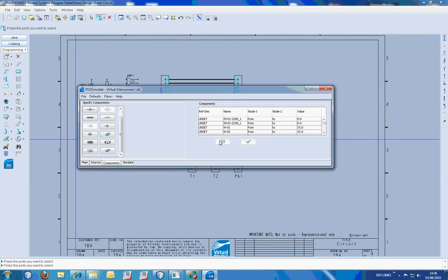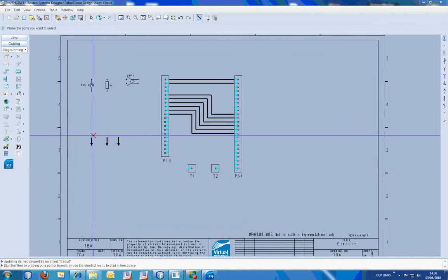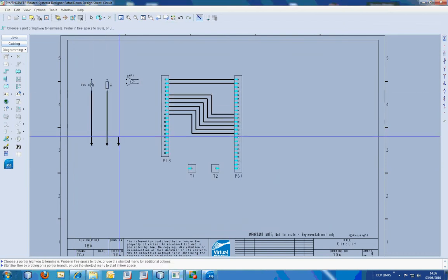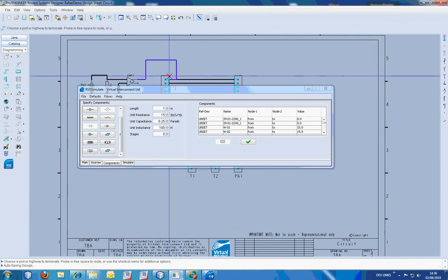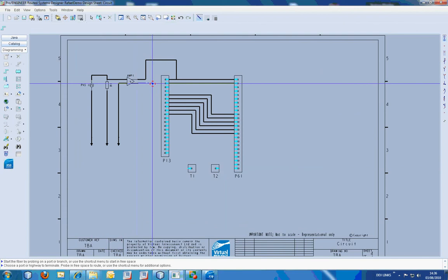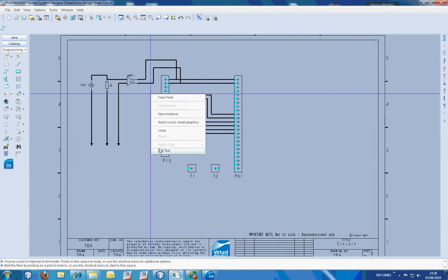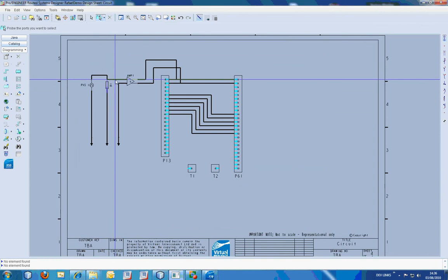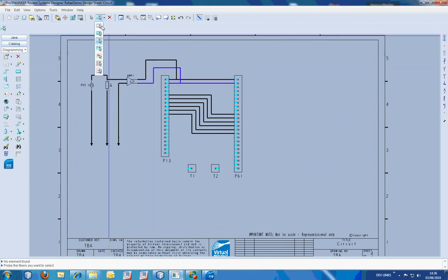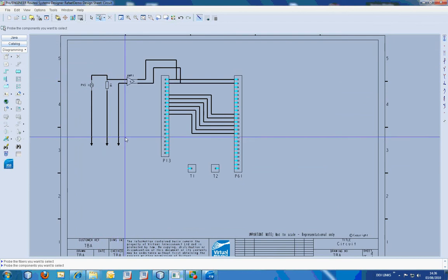And we'll just instance some fibers through the simulator and wire all these components up. And we'll finish this side by wiring the components into the connector block. And as you can see, if we select some of these fibers, RSD has created a signal network routing between each of the different components. Now, the signal network will become important when we come on to moving to a wiring sheet from this circuit sheet, and we will come on to that later on in this demonstration.